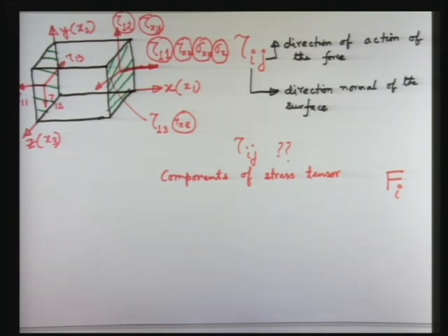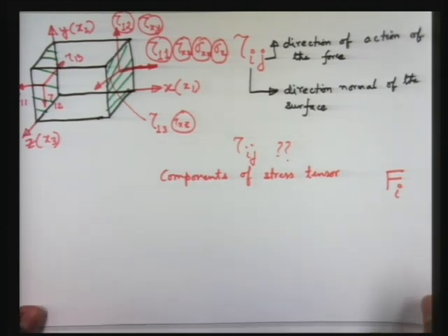we have understood that there are normal stress, the normal component of stress, and the tangential component of stress, and these stresses are important when the fluid is at rest and even when the fluid is deforming. So if the fluid is subjected to a tangential stress, a fluid will be deforming no matter how small the stress is. But if the fluid is subjected to a purely normal stress, then the fluid will be at rest, and that is a state of hydrostatic stress, and that will be covered by Professor Sandipan Ghosh Maulik in his lecture. So I am not bringing that out in the purview of this particular discussion.